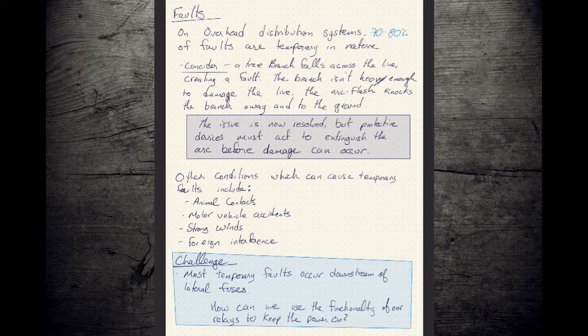So the challenge to this is that reclosers and breakers are really expensive compared to fuses. So you can't just put them at every lateral. The other big challenge that we face is that our main three-phase bus, we tend as utilities to take really good care of it. You don't end up with trees growing up into your three-phase overhead on your main bus. They're well back from the roadway. Or if it's a really exposed area, you'll put up a bollard, which are those concrete metal posts that sometimes protect stuff in parking lots or along roadways where people are worried about someone smacking into it.